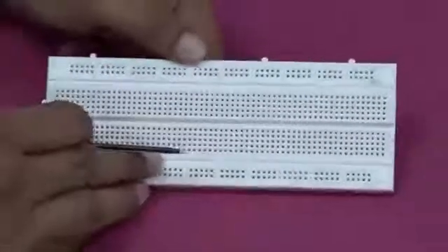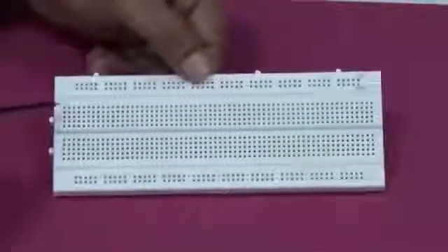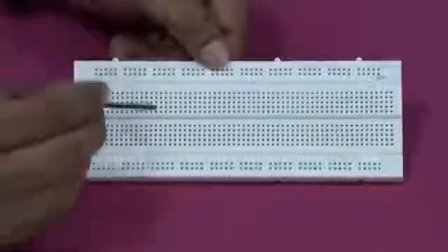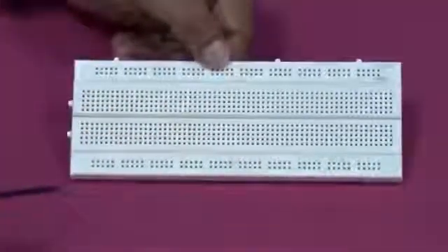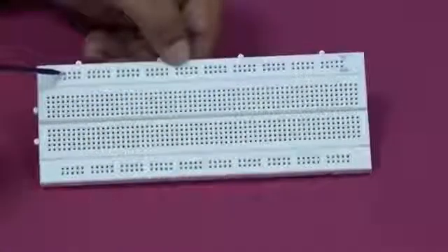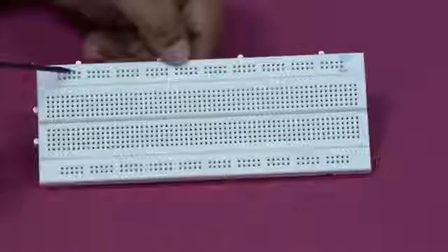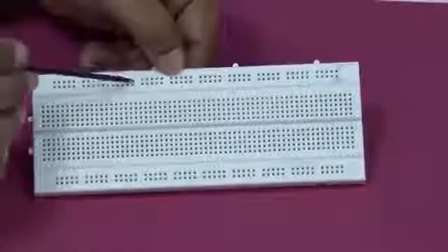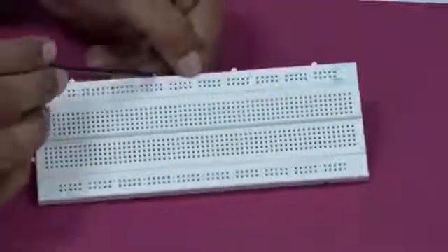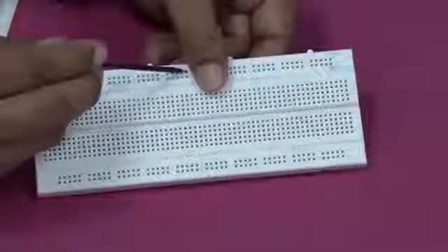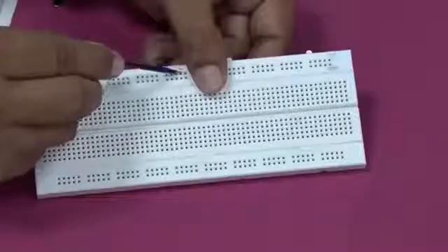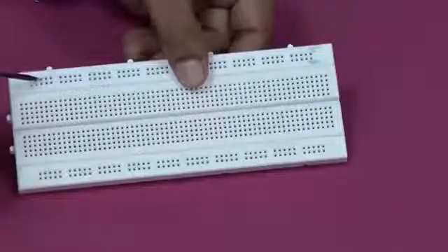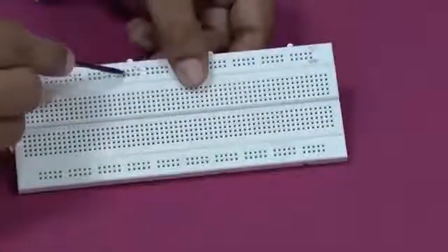In this breadboard, you can see there are so many holes here. You can all see this is a hole, this is a hole, this is a hole. All these are holes. There are some holes here, there are some holes here. So too many holes are there. Here you can see there are 1, 2, 3, 4, 5 holes here. Then on the same longer line, you have 5 holes here, 5 holes here, 5 holes here, and so on. So all these 25 holes on the upper line, this 5, then this 5, then this 5, this 5, this 5, all these are connected to each other internally.